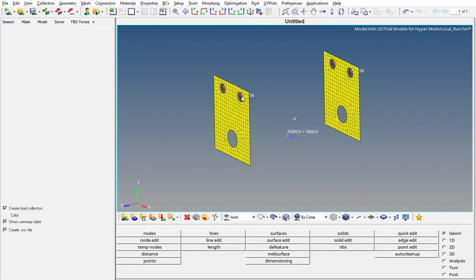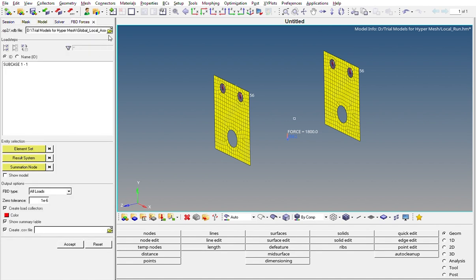Here what we have to do is select the .op2 file, the .op2 or .xdb file which is generated on the run. If you remember, I told you we'll be extracting three outputs, H3D, HM and OP2. That OP2 file was needed for this purpose. So this OP2 file we'll take from here, and then we'll select the load case, like the load step, which we have used.